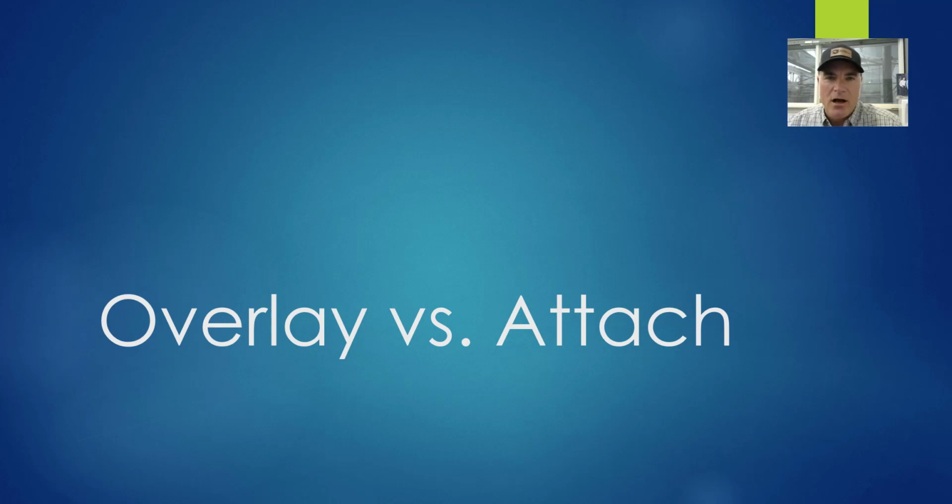In this video, we'll be talking about the differences between overlay and attach. Overlay and attach are two options for inserting external references, or XREFs, into a drawing, and they differ primarily in how they handle nested references. It's important to know the difference so that you can avoid the problem of circular references. Let's get started.